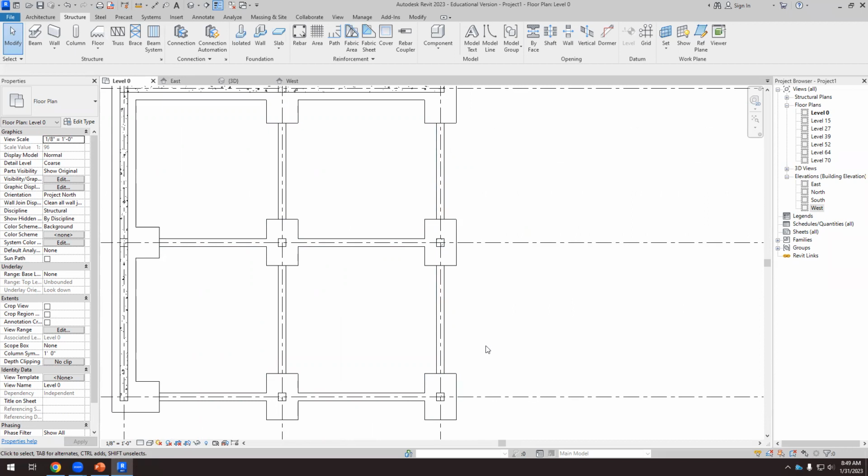If they weren't connected, if there's an extra load here, or there's some weakness in the soil here, and this column goes down just an inch, so that inch will show up somewhere. Okay, so if we have columns here and one of the columns goes 1 inch down, then the rest of the structure has to adapt, and we will end up having cracks around the column.